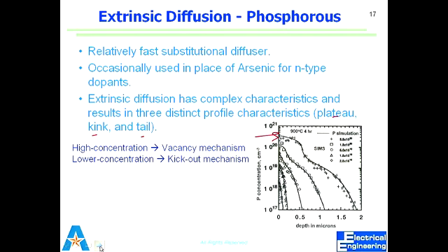So this is probably the region that is of our interest, but this region is just causing a deep profile for the doped area. So this is again depth. If I want to get rid of this part, then the only way is to reduce the doping concentration. So that's again opposite to what we want. We want a highly doped area.